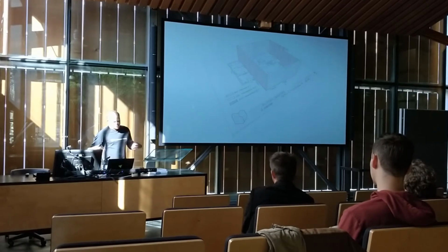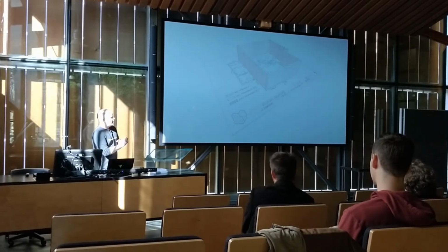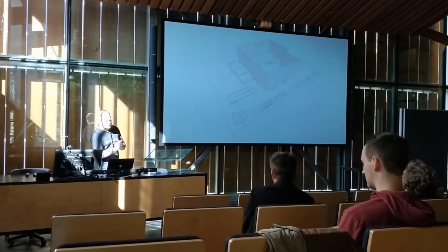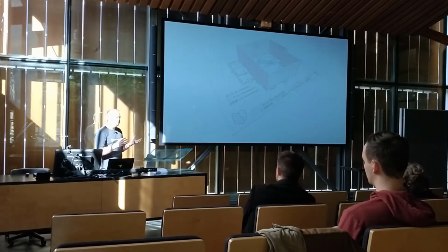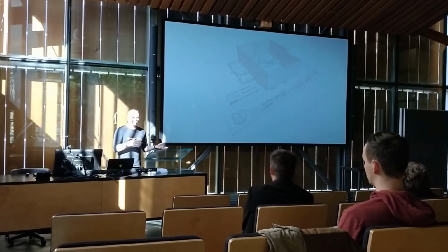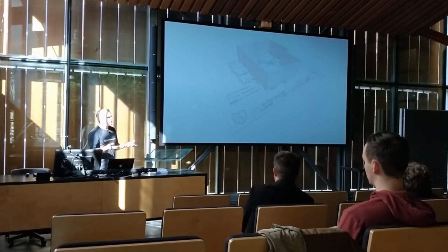I can tell you that when you extrude your plan horizontally using the push-pull tool, the push-pull tool cannot draw off axis. It will only push and pull perpendicular to the surface. So it's a fail-safe that makes sure that you do not build geometry off axis. Because if things get off axis in SketchUp, it can be fixed, but it's certainly not fun to fix. And if you just stick with the technique, it works every time.